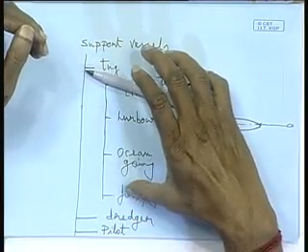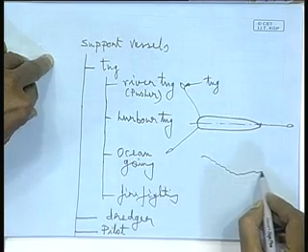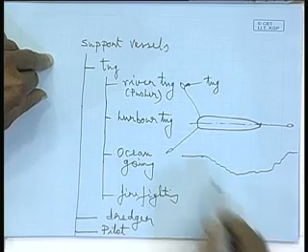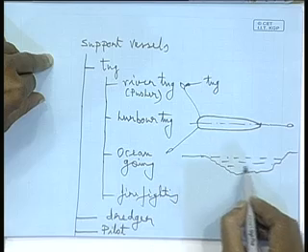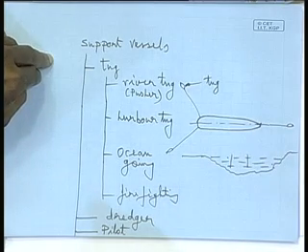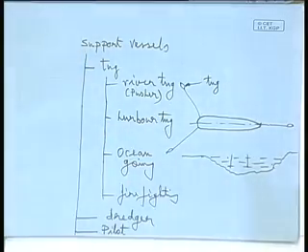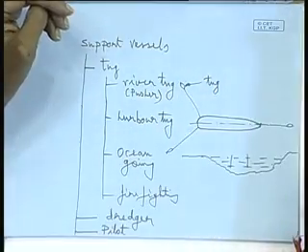Because as I said, dredging doesn't mean that the entire river geometry is dredged. Say the river bed is something like this, right? Everywhere you do not have sufficient draft. A certain region probably you are maintaining navigable. You cannot go on dredging the entire width. So within the river or within the channel, a navigable canal is maintained, that the pilot knows very well. So he takes over. He guides the ship through that navigable canal.